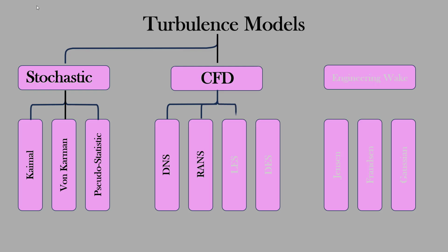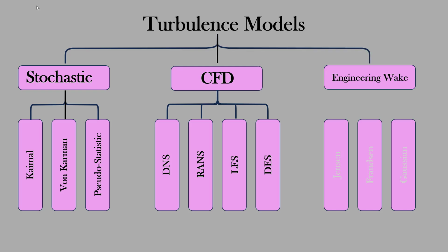So stochastic is similar to when you have statistical methods being used or pseudo-statistical methods. So it's partially statistical. You can use the mean wind speed, you can use the standard deviation. Then other parameters are used to model this wind. In most cases, these kinds of parameters are in two-dimensional space. You do not have it in time space, so it does not vary according to time or in distance. It's just at a plane. It's just plain two-dimensional wind data that you can generate.